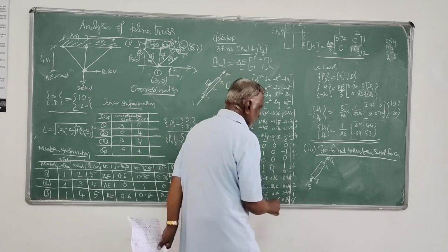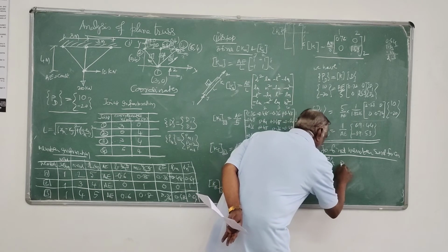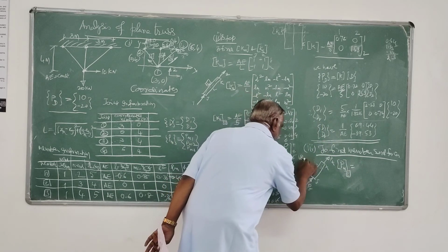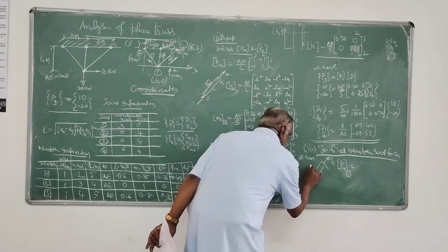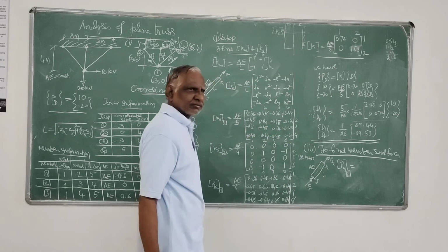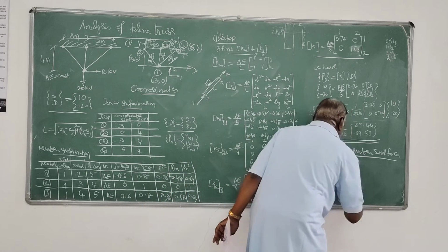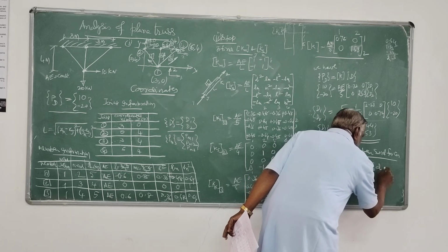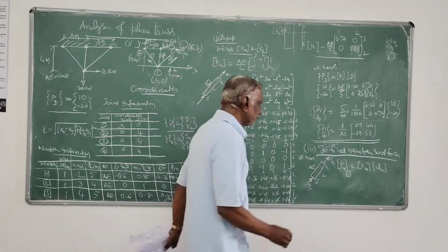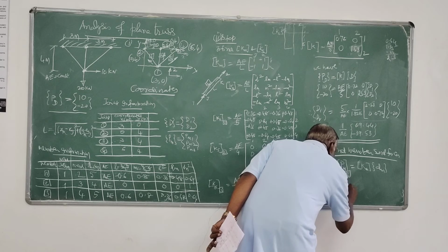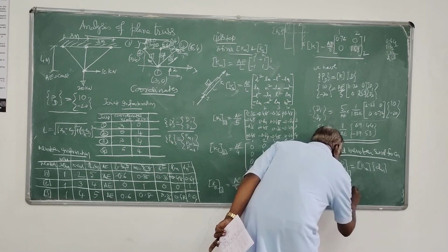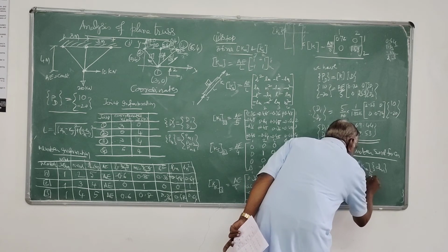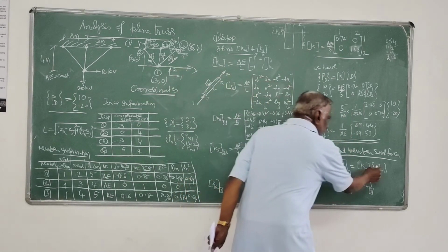That is a very simple process. We are determining this PM, for any member I, where AE is the axial rigidity of the member and L is the length of the member. PM is given by Km into DM. Again, you can write that PM of member I is given by Km of that particular member I into DM.